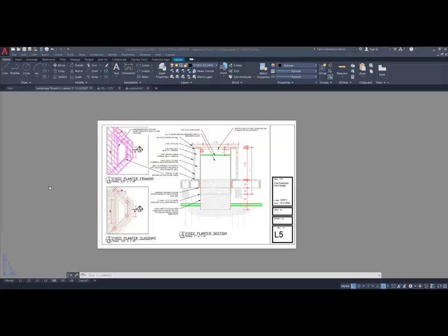So after some consideration, here's my final example of what I've put together. I determined that it was very important that I show the framing and the base plate and how it will be attached to this, as well as this perimeter header, which I mentioned in my notes here. So here I also identify the opening sizes, which is critical for the builder to lay that out. You'll notice the opening sizes in here are slightly different because there's an overhang between the opening and the actual lip of the top of this double top rail planter. So those dimensions should make sense.